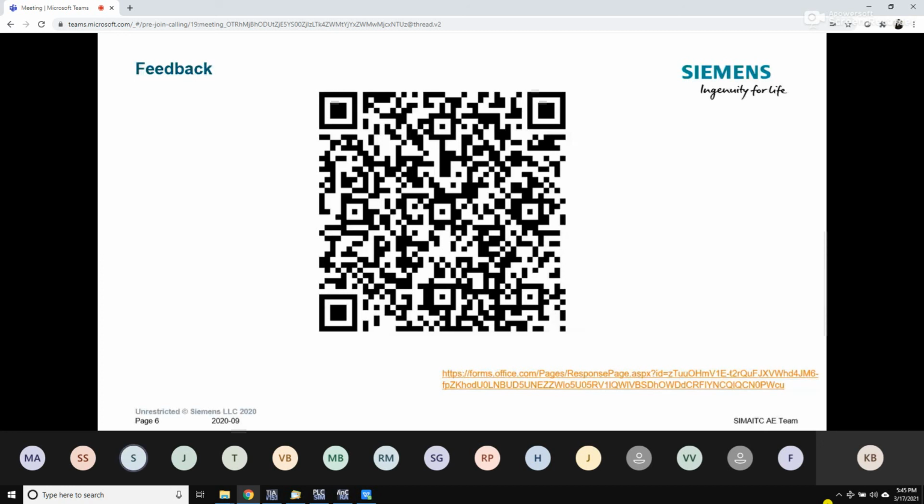Can we use the AT instruction in an FC, and can you explain the IDB, why it is mentioned as set in IDB? This is really explained in the link that I'll be sharing with you. Why the AT instruction needs that IDB, and how and where it can be used, is all explained in that FAQ that is pasted. So I'll definitely share that link as well.